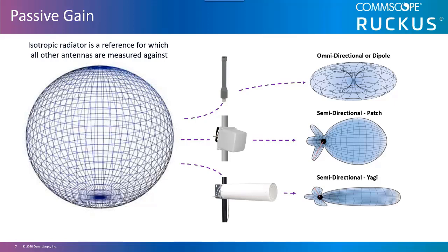The gain of an antenna is created by the elements which make up the antenna, allowing all of them to focus the RF energy in a specific pattern. The gain of an antenna is measured in relative units, dBi or dBd. The antenna adds a fixed amount of gain due to its construction. If you supply more energy at the intentional radiator, or supply less energy at the intentional radiator, the antenna's amplification factor remains the same. If you have a 10 dBm intentional radiator using a 3 dBi gain antenna, the output will be 20 dBm or 100 milliwatts, as you learned in the RF math module.